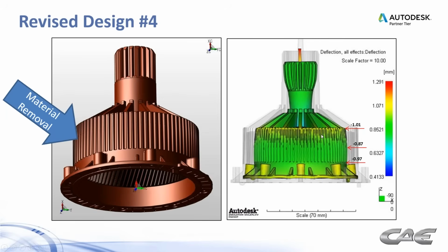So the final design that we landed on was this design, much easier to tool. We essentially cored material out of that thicker wall and those sidewalls there, and we're able to produce that outward bow and reduce the magnitude by quite a bit. So you see the power of playing what if here, and again hardwiring it into the part design to get the effects you want. And so in this case, this particular part design will work over a wider range of process settings than the original one did.